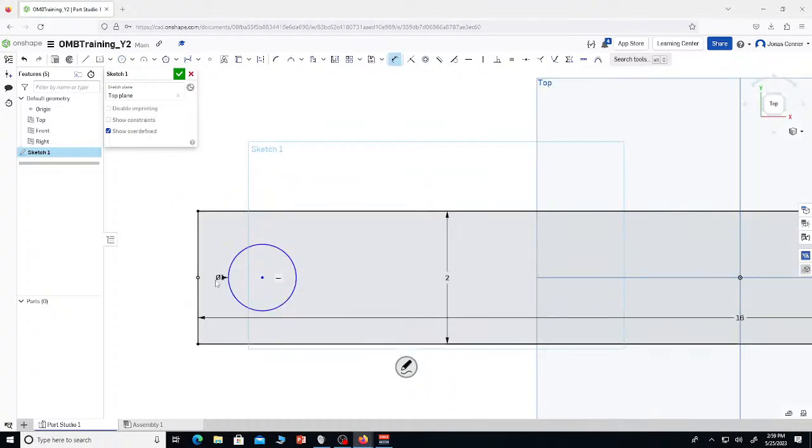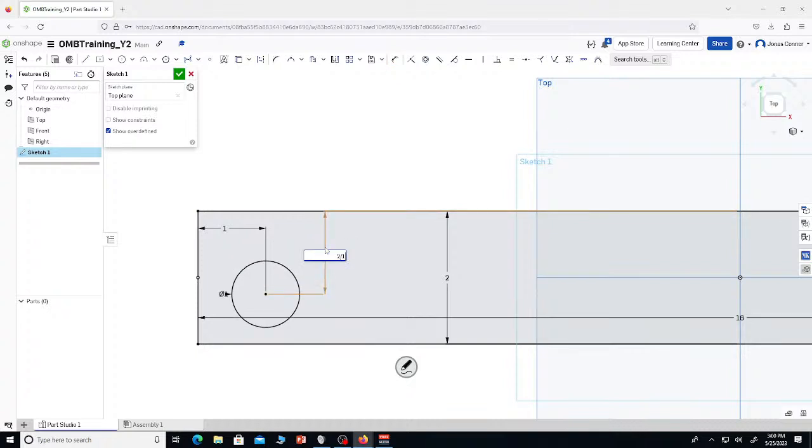So then I can define the distance between this and this to be 1 inch. And I don't have to create a definition between here and here because it's in the center. Of course, these are constraints that pop up. I could delete this horizontal constraint and then say, okay, I want this to be 1 inch, or I want this to be 1.25 inches or something like that. But I can say 2 divided by 1 inch is 2 inches. I can say 1 divided by 2, half an inch. 1 over 1, 2 over 2. I can do any math, say square root of 1.